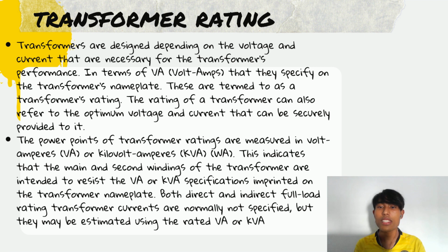A transformer's rating also is determined by a rising temperature, which is determined by the transformer's losses. The temperature may be kept below acceptable levels with the correct cooling system. If the cooling system is in good and effective shape, then the higher the rating of the transformer will be. The rating of an electrical machine is indirectly defined mostly by losses existing in the machine for a certain cooling system.